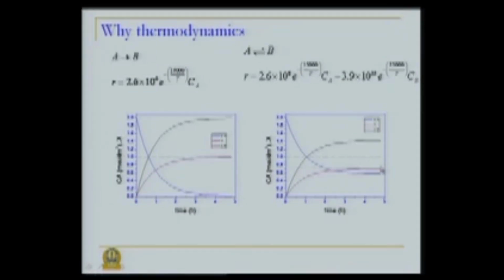No matter what we do, that means continue the reaction for longer times, nothing is going to change. The concentrations are going to be at these respective levels, conversion is going to be same. Or in other words, now we have saturation not at the complete consumption of the reactant, but saturation at some partial consumption of the reaction.